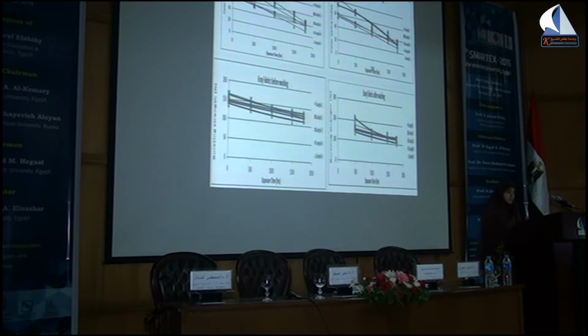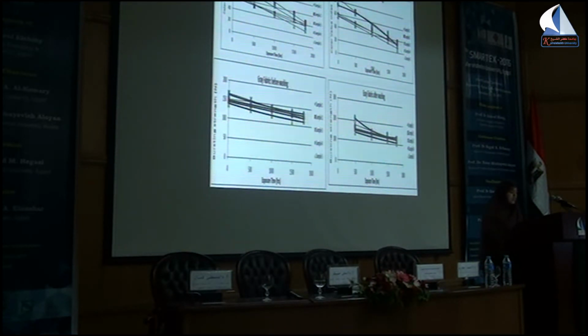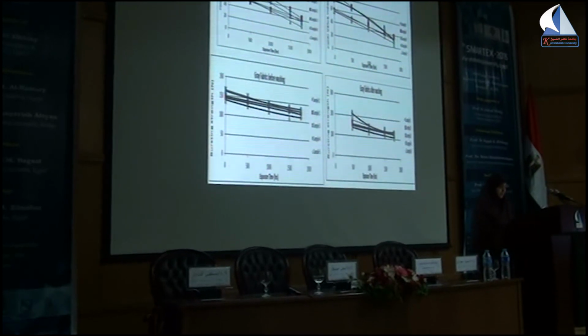The first 2 figures show the effect of exposure time on color value before and after washing, and the second 2 figures show the effect of exposure time on bursting strength. As we see in the figures, as the exposure time increases, the color value decreases before and after washing, and the bursting strength also decreases.